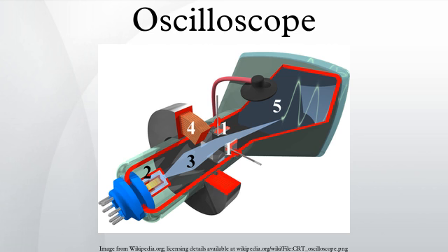It is desired to set the scope to only trigger on one edge per cycle, so it is necessary to set the hold-off to be slightly less than the period of the waveform. That will prevent it from triggering more than once per cycle, but still allow it to trigger on the first edge of the next cycle.